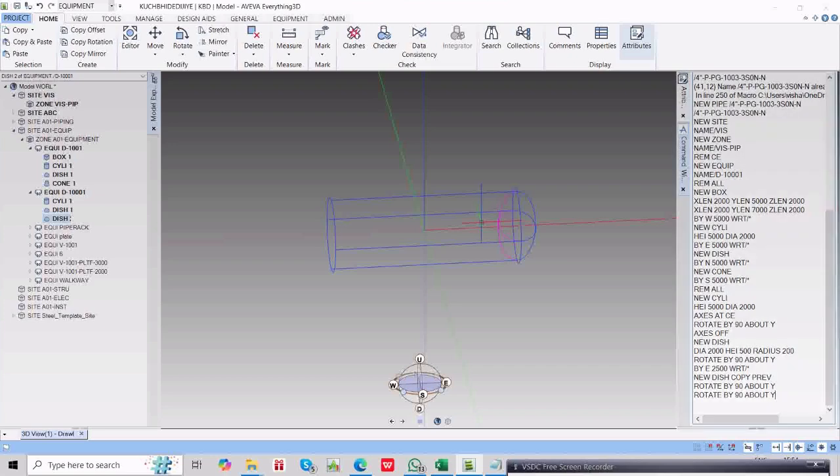And then you need to move this one here. So previously I showed you how I moved it with the command method by east 2500, or else this time you can use this command by west 5000. Okay, this will also work. But for example I want to move this one with the manual method.